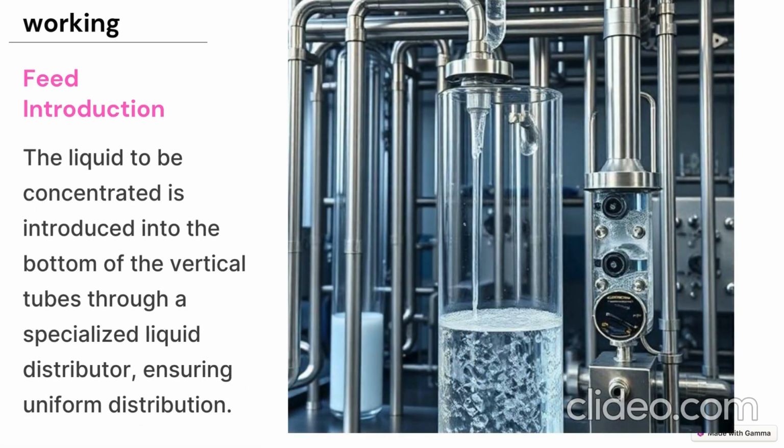Working of climbing film evaporators. Now the sample, or you can say the liquid which is supposed to be concentrated, is introduced into the bottom of the vertical tubes. That means the sample is introduced from the bottom of the vertical tubes through a specialized liquid distributor in order to establish a uniform distribution.